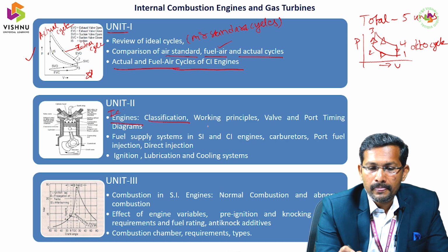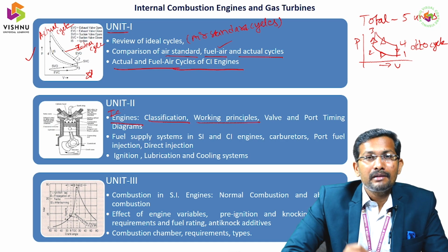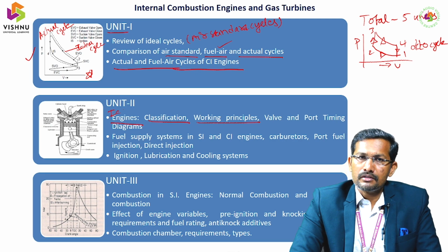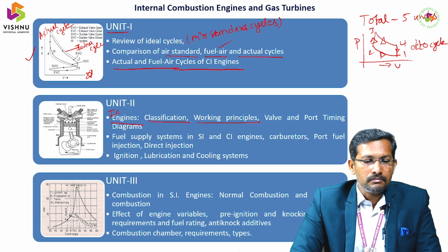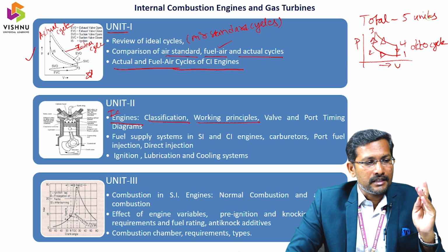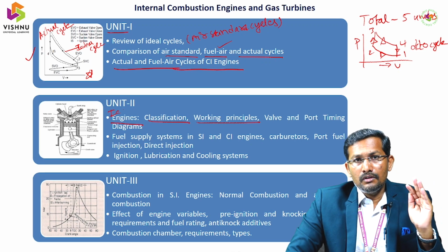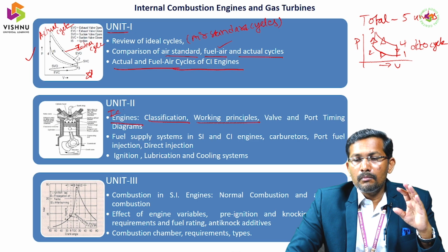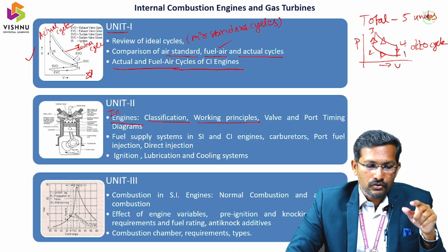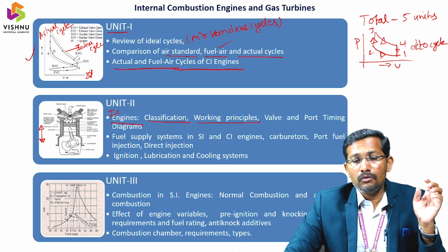That part we can see. Next one is the working principle. This is most important. The working principle of an internal combustion engine is very simple. It works based on 4 strokes: the suction stroke, compression stroke, expansion stroke, and the last one, the exhaust stroke. To complete the cycle of 4 strokes, the piston is moving up and down, undergoing the 4 strokes.